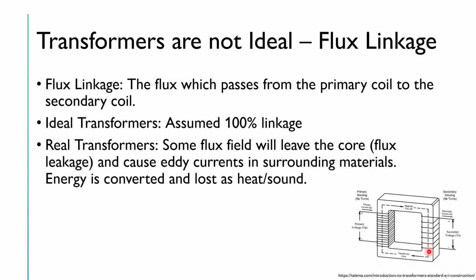In actuality, this is not completely the case. What will happen is that some of the flux will leave the core, and we call this flux leakage. What that leads to is eddy currents being generated in surrounding materials. And as that flux leaks, we end up getting an energy conversion from that original electrical energy from the primary coil, which ends up turning into heat and or sound energy.